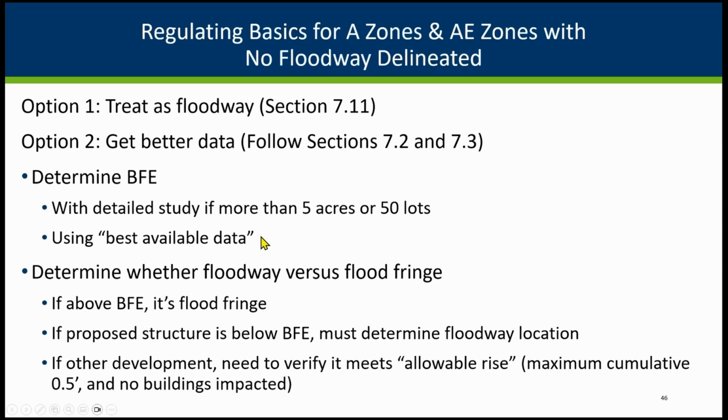If you haven't already figured out the BFE, that's going to be part of the process. For instance, in some of these areas, we do have the mapped floodplain. We'll be showing some areas that are actually above the BFE as part of the floodplain, and it's not following the contours. It was done earlier before we were using all the LiDAR.